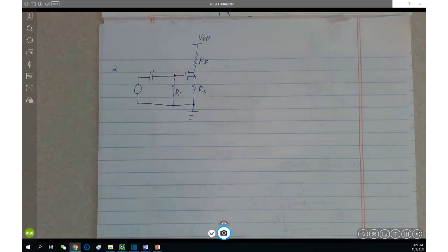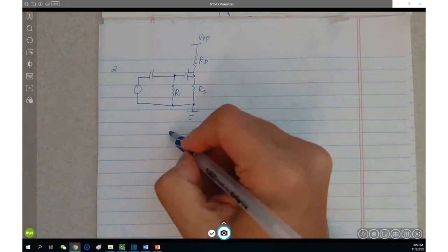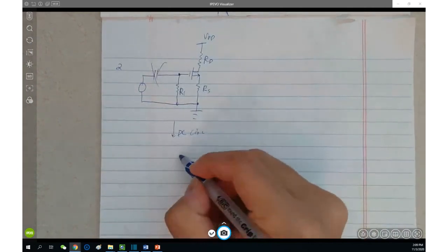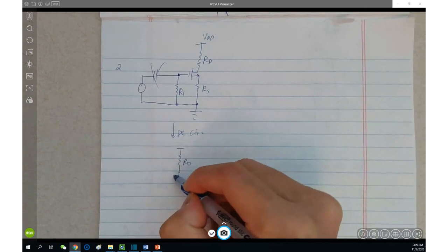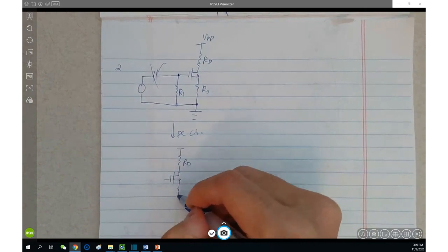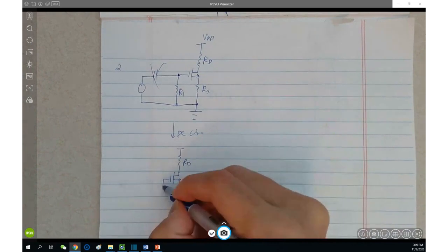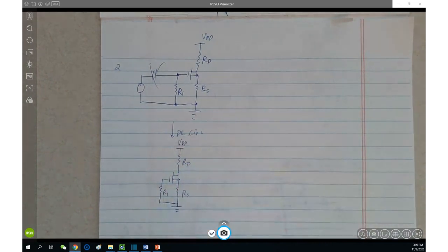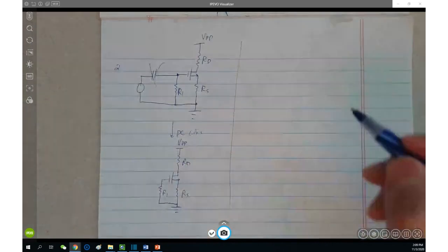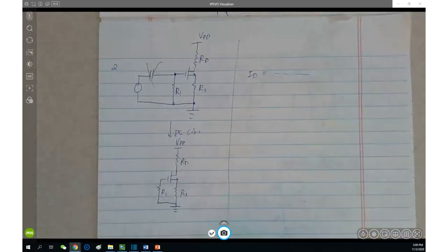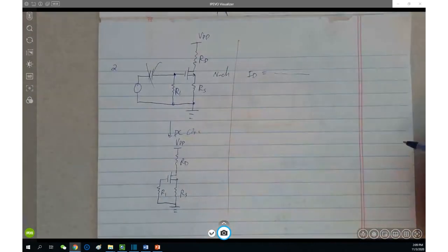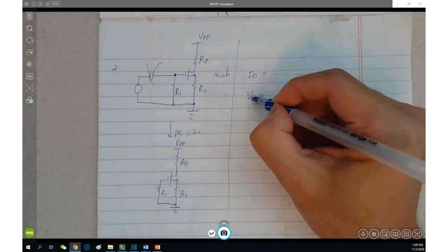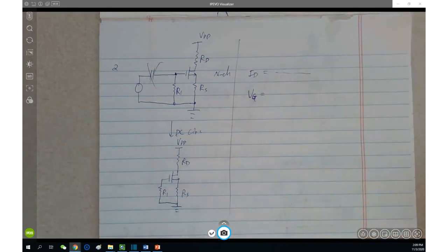Right, so following a similar idea, the DC circuit looks like what? Open here once again. So we have RD, RS, and the ground. R1 here. This is the DC circuit. And therefore you have the ID equation, N channel. That is still N channel. ID saturation equation. And second, this time, what is VG? 0.